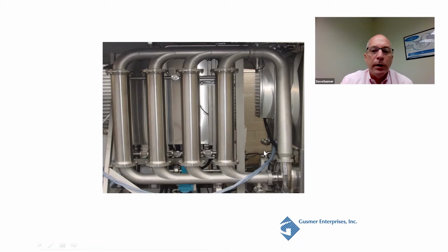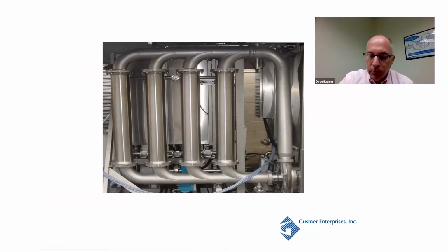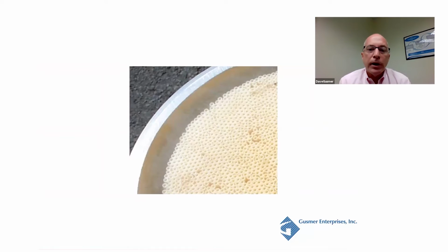We're flowing the wine through the centrifugal pump here, and we're flowing it from the top down. The only place for that wine to go is to either stay in the loop or to go through our membranes, which I'll show you in a second. For this next slide, we took one of these 4 modules off the system. You're looking at it from the top down. What you see here are about 2,200 capillary straws. These are our membranes. This is the actual membrane material.